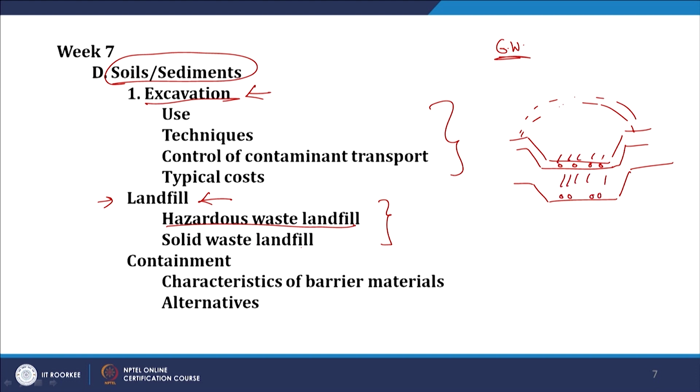and so on, let us say, right, and such that the leachate that we generate from the landfill does not reach the groundwater table or level here, right, does not reach the groundwater. We are going to capture it above the first impermeable layer, and if over time some amount of leachate reaches the second layer, we are going to have to try to capture that too.